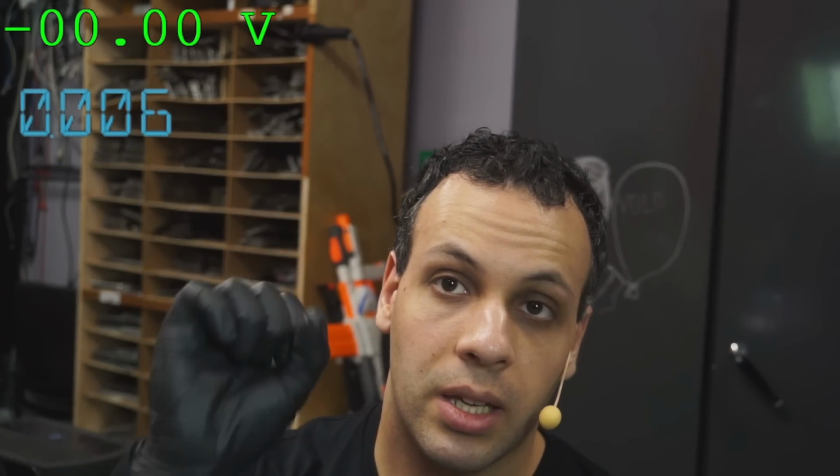This is how many amps it was taking without the battery plugged in. This was my problem, so that you can associate it, and then in the future, you save time on troubleshooting. That was done. Beautiful. Great. Then we figured out that that was actually missing. We looked around the board at the typical culprits for a missing PM Sleep S4L. Clock, not there. Short circuit, not there. U1950, ow. Burned, destroyed, replaced.